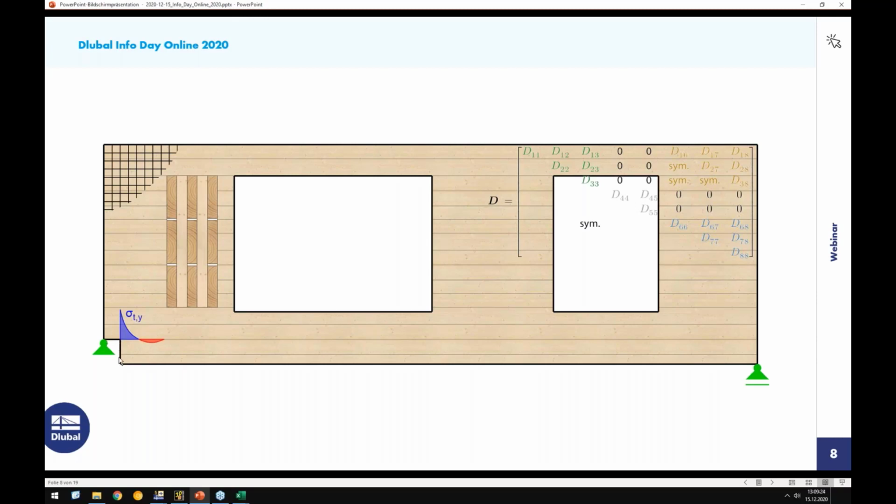Okay, we have a tiny notch here on the bottom. Of course, it will not be controlling since this element is really high in ratio to this small notch. But you can imagine when you have a CLT element as a beam, and maybe you can extend this line here, then you will see you have around 50% of the notch, and then it is much more controlling, and this fact needs to be checked. I'm just saying that you should consider it.